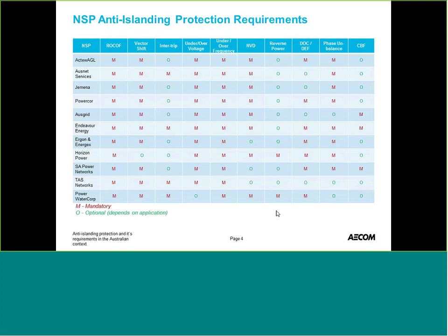But generally speaking, things like rate of change of frequency is required, vector shift is quite often required. We've seen some cases where it can be negotiated out. Quite often with vector shift we find nuisance tripping is an issue, and you end up changing your settings so much that it basically desensitizes it for a genuine islanded condition.